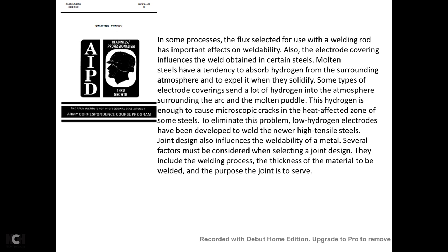The hydrogen is enough to cause microscopic cracks in the heat-affected zones of some steels. To eliminate the problem, low hydrogen electrodes have been developed to weld higher tensile steels. Design also influences the weldability of the metal. Several factors must be considered when selecting the joint design.